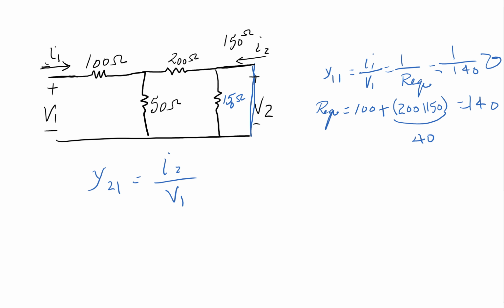So again, to do that, we have to do a KVL. Probably it's the easiest way to do it. So this goes away, if you notice, because it's a short. Any resistor in parallel with a short doesn't see any current, so might as well put it that way. And then, just to not get confused, we're going to call this one IA, we're going to call this one IB, and we're going to write the equations for that. So IA is equal to I1, so we can just literally plug it in, so we don't have to do one more insertion.